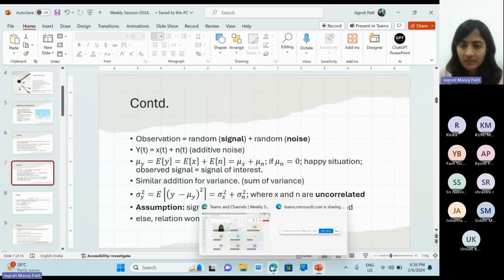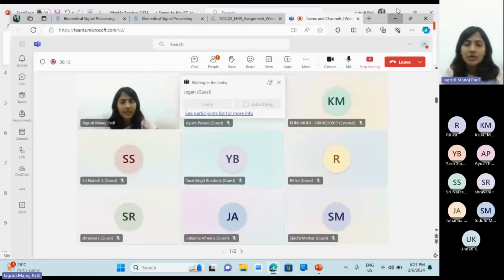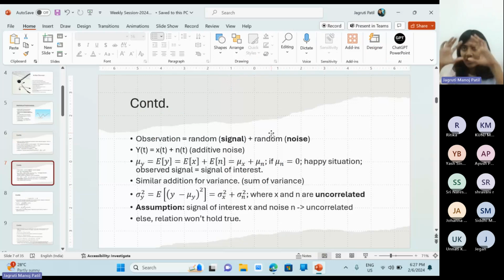Are the waveforms gated or not, or are those clipped or not? So at first, what you see is that the waveform comes, it fluctuates, and then it normalizes at the baseline, the horizontal origin line. What we see there: the first is the signal, next is the noise, but both of them are random, because if you see it in sample mode, you can see that it's fluctuating continuously. But if you average it for n number of times, say in the order of 2 raised to n, depending on your type of system, you'll see a nice smooth waveform.